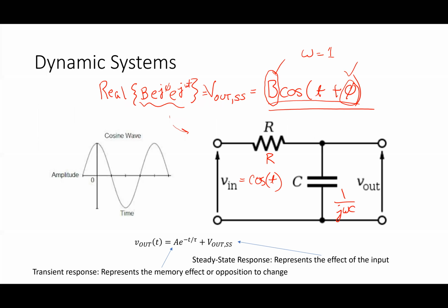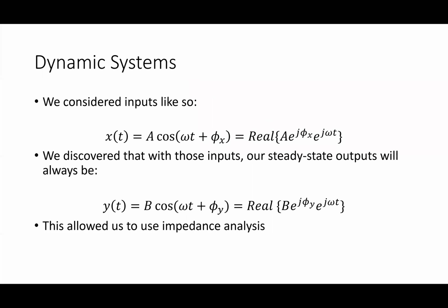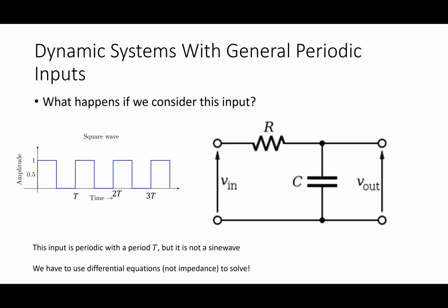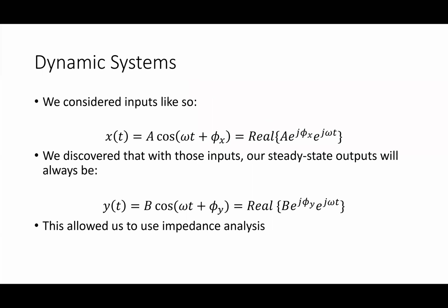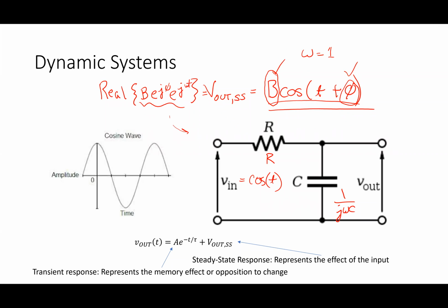All right. So we talked last time about the idea. Let me go back, I guess, just to here. We talked about this, my introduction to this, was to say, okay, if I've got an RC circuit like this and I have cosine t as the input, one way to do this is to do differential equations. In other words, if I want to know what V out is, if the goal of this problem was, okay, I'm going to put cosine omega t as my input, what's my output voltage across that capacitor? One way to do this is to do a differential equation.